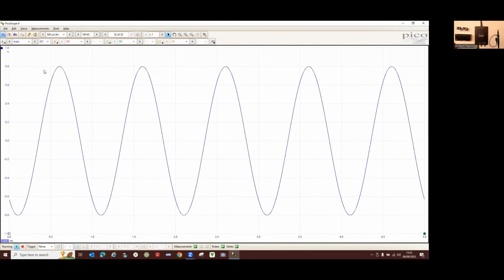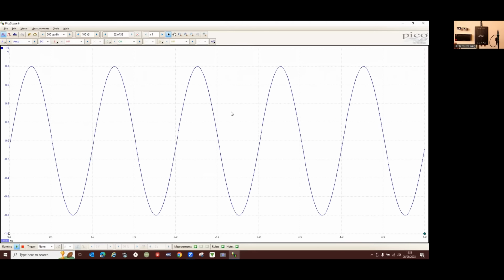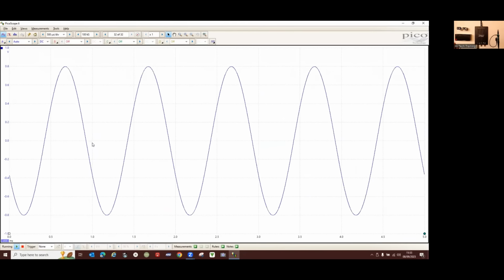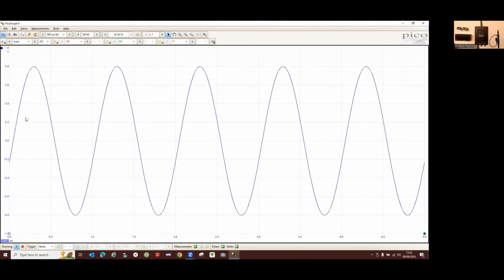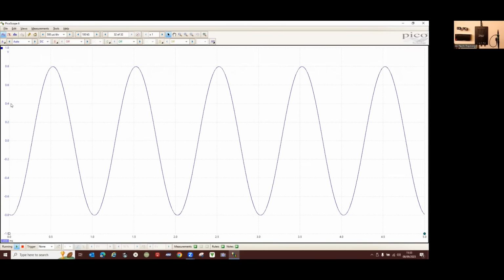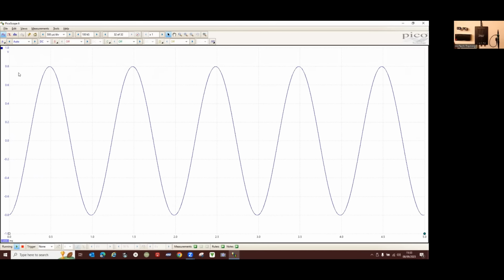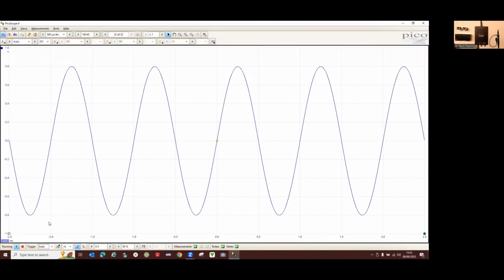And we're showing there an AC volts coming in. Yes, AC. It's up and down and up and down and up and down. So AC means changing. So here in the center of the screen, you've got 0 volts. You go positive and you go negative. So I'm going up here by about 0.8 of a volt up and 0.8 of a volt down. Trigger none, so I'm going to put a trigger on there. Hopefully this should stop all the jumping around.